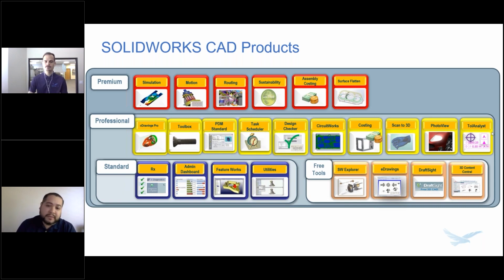Yeah. The benefit though of having both products, the structural, whether it's from SolidWorks Premium or the higher levels, is that they do communicate. That's really the key thing, is that these SolidWorks tools communicate with each other, where if in the full-blown flow simulation study you ran a thermal analysis and you wanted to see the thermal stresses, you can throw those thermal results from flow into your structural analysis and see how much it is going to thermally deform and stress based on those thermal results.